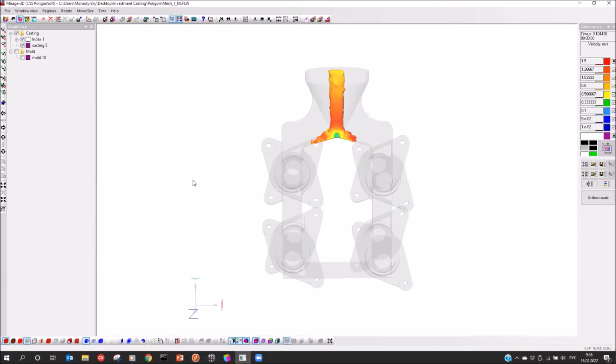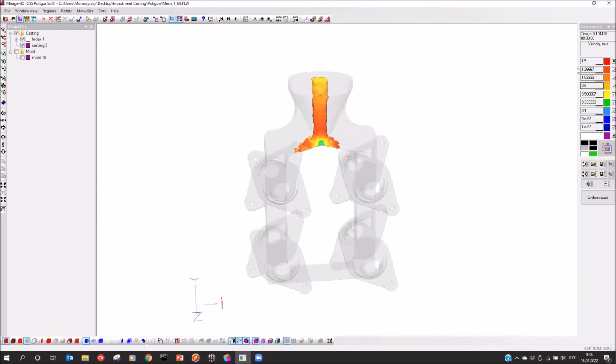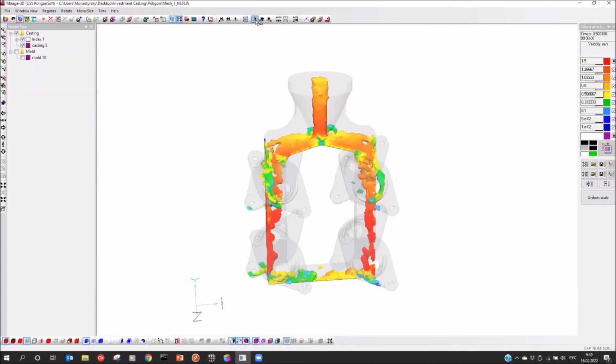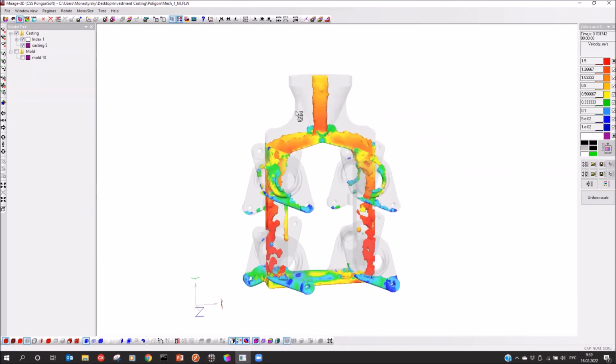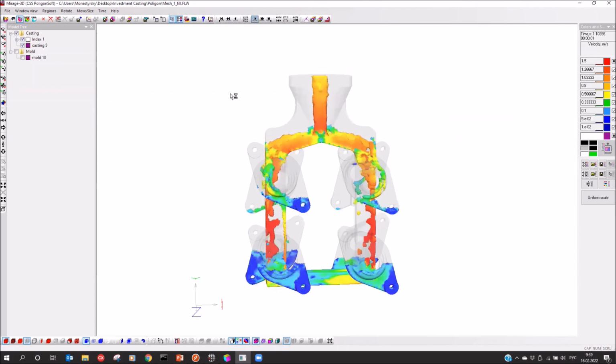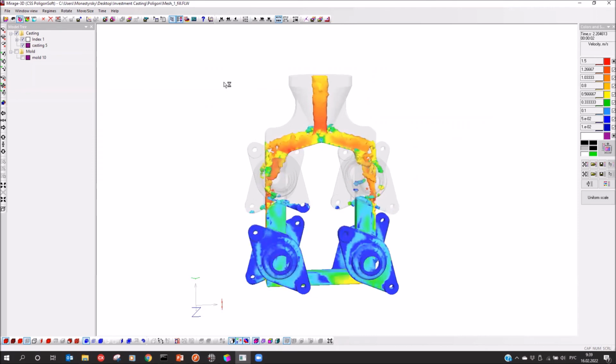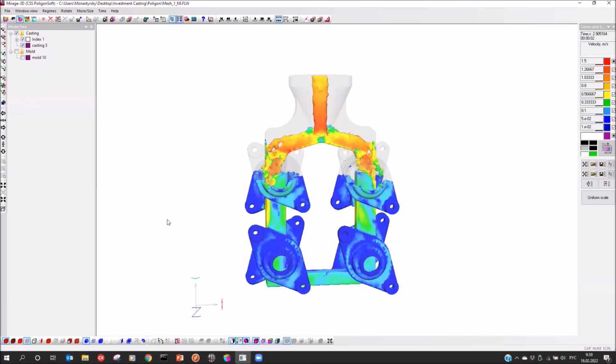Our simulation is finished, and we can show all results. Now we see filling results, and we see the velocity field, and here is a scale, and we can use this player to move along the simulation. See filling dynamic. Looks like this. Or we can use automatic mode. If geometry is big, we can record video and look at the filling process in real time.